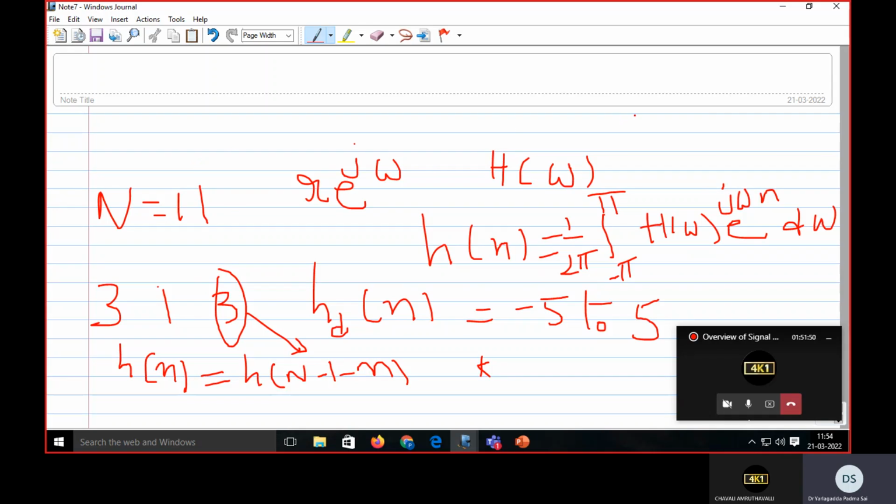In DIF we are not doing that initially, even and odd. First we are splitting the summation based on even samples or odd samples. Now here I am considering odd samples. Because of that, the first three terms form one group, the center term is one, and the last three are another group. After that, for the second summation I am imposing the symmetry condition, modifying my summation, and after simplification I am applying the cases where k is even and where k is odd.